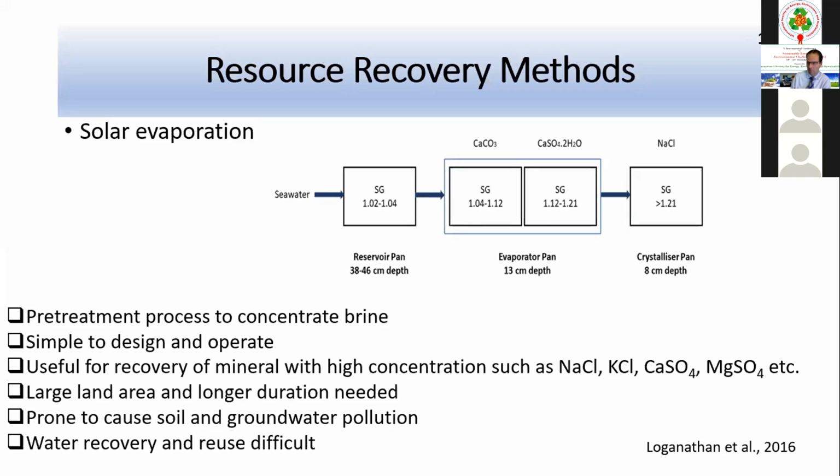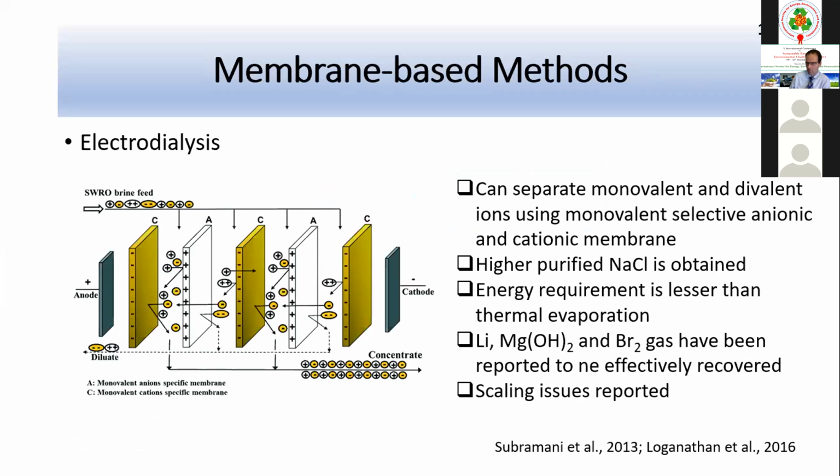It is basically a pre-treatment process to concentrate brine, and it is simple to design and operate. But the key issues are that it requires a large land area, a longer duration is needed, and it can cause soil and groundwater pollution. It can be useful for minerals with high concentration like sodium chloride, potassium chloride, gypsum, and magnesium sulfate. But there is no water recovery opportunity there.